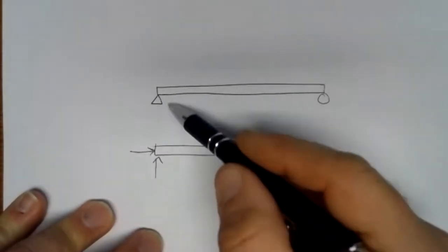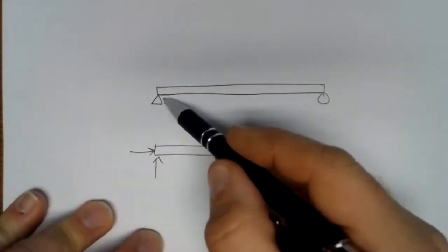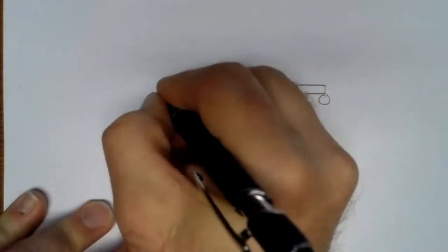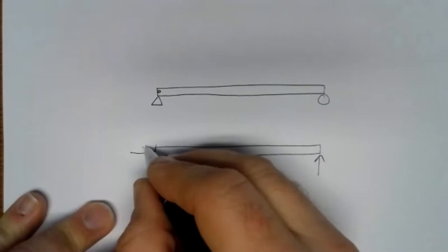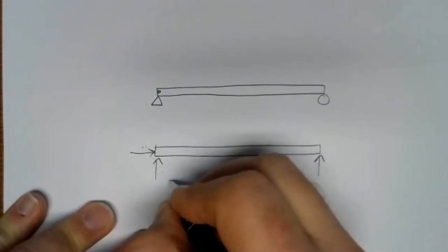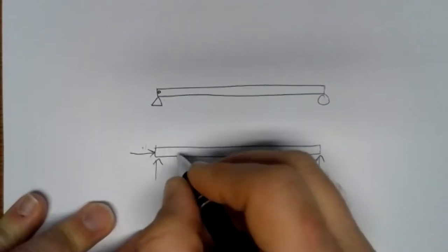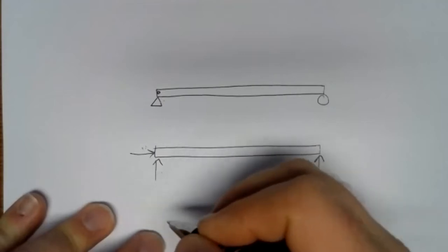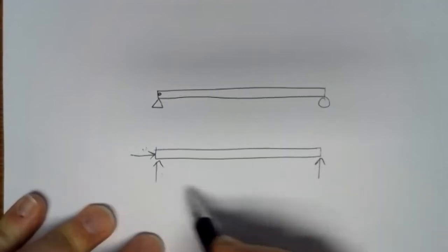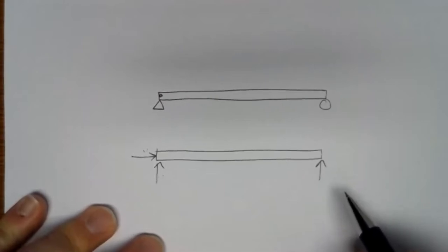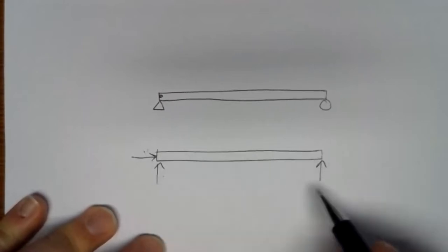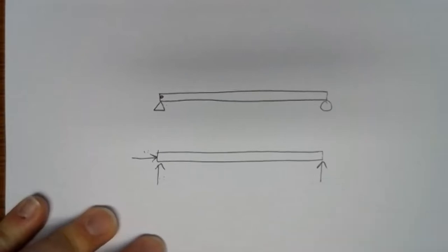Well, whether that pin is shown as a triangle, a hinge, or whether it's shown as just a point, it still contributes two unknown forces. There's a force in the x direction and there's a force in the y direction. So each pin gives us two unknowns. And if we have a free body diagram that's non-concurrent, we can handle up to three unknowns because we have three equations: the sum of forces in the x direction, sum of forces in the y direction, and sum of moments about a point. So we're going to use that.